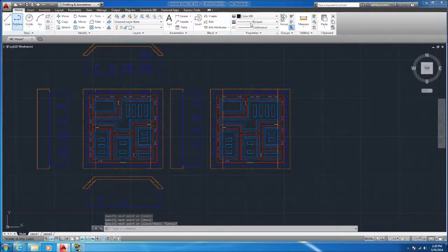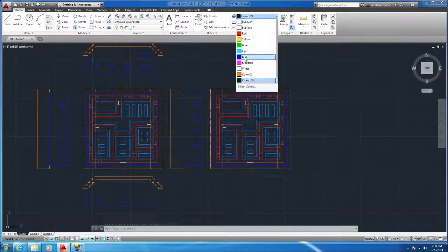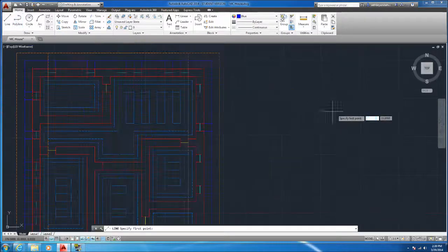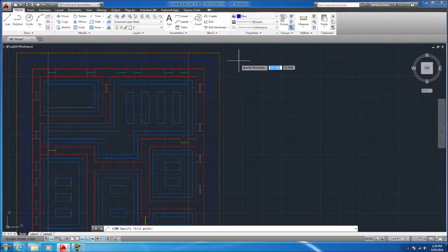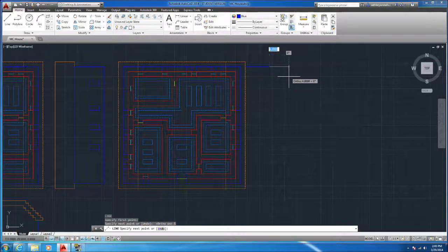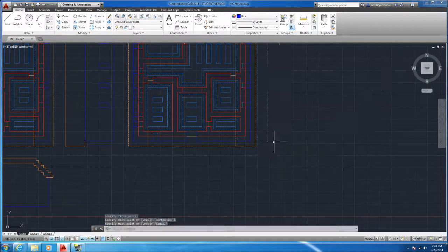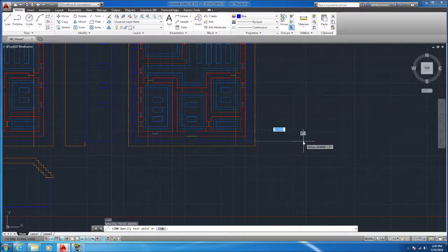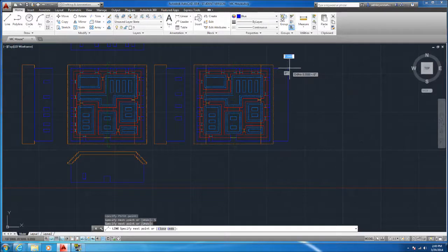Okay, now we actually start to draw. So we're going to go back to blue. I'm going to start on our exterior wall here. So 1, 2, 3, 4, 5. Alright, dang it. Ortho, there we go. Pretty much we're just going to start off like an elevation again. And pretty much a section cut is an elevation, it's just a more detailed elevation.